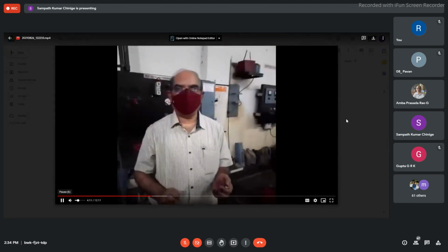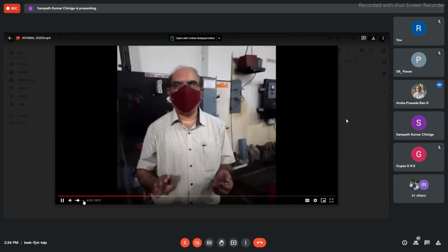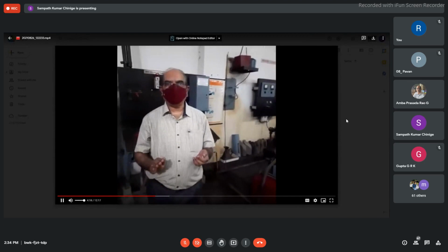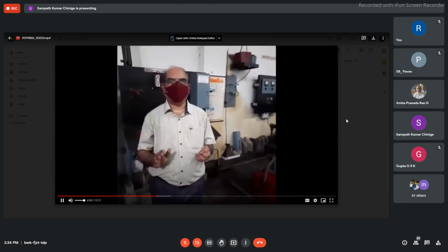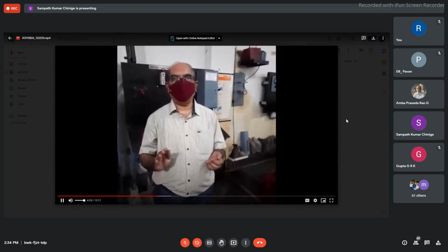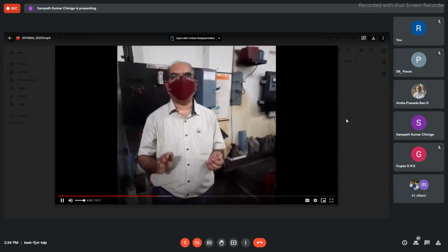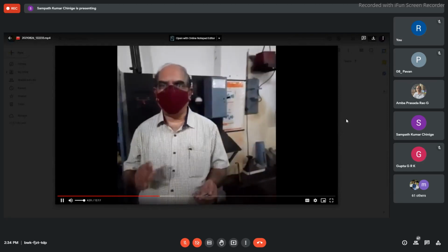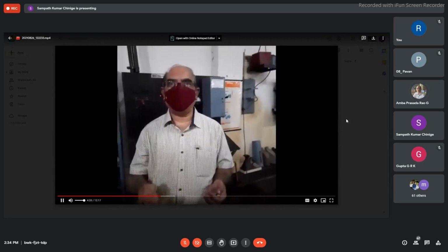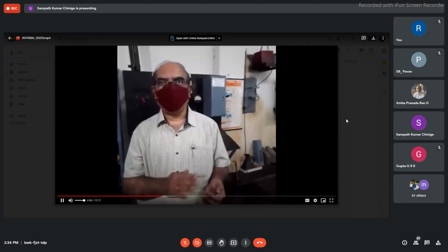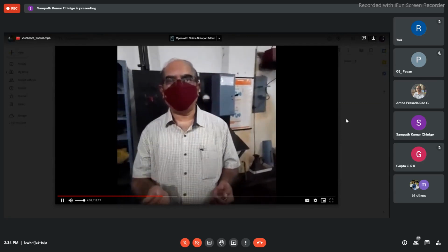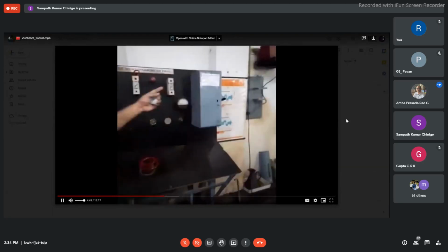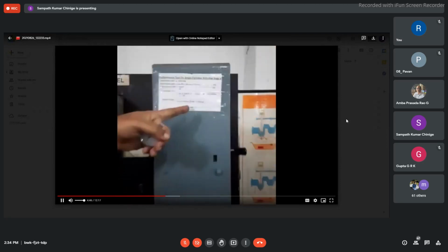The nameplate details of the engine will help us to calculate what is the load by which I can load the engine, so that the engine will develop a power equivalent to 5 HP when it is allowed to run at 1500 RPM by supplying the fuel. So for observing the engine behavior at different loads, you have to divide the maximum load obtained from that formula, 2 pi NT by 60, multiplied by some conversion factor, equivalent to 5 HP. So we will be able to get the value corresponding to this 2.42 kg meter.